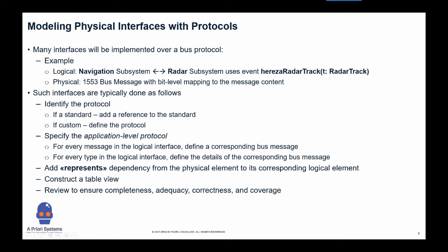The Harmony process, or Harmony work profile, contains a stereotype called represents, which we will use to trace back from our physical representation to our logical representation. So you could use refine for that. Refine, I think, is subtly different, and refine doesn't cross abstraction layers. And this really does cross abstraction layers. So I created another stereotype called represents. If you want to use refine, I wouldn't yell at you too hard.